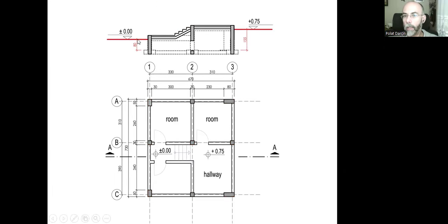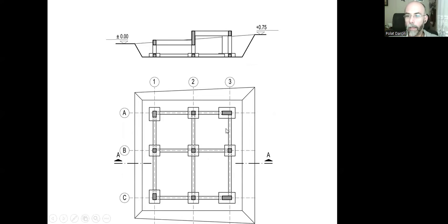So that's how we can do that. We can start from this right side, go for 80 centimeters deep, and that will be the level of all the footings, even if the other side needs to go more than 80 centimeters towards the inside of the earth. That will be a better solution. And since the area is sloped, when we do the excavation, there will be differences with the sloping sides of the excavation like that.